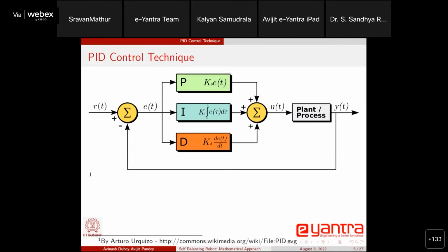So we start by introducing the proportional gain till there is an oscillation in the system. Once the oscillation starts, we bring the KD into the picture, which tries to reduce the oscillation. Fine. So KP takes us up to the desired output, but once it reaches the desired output, we further increase it so that a little bit of oscillation starts. So we are moving about our desired input. Then we introduce the KD, a gain which is proportional to the rate of change of error.